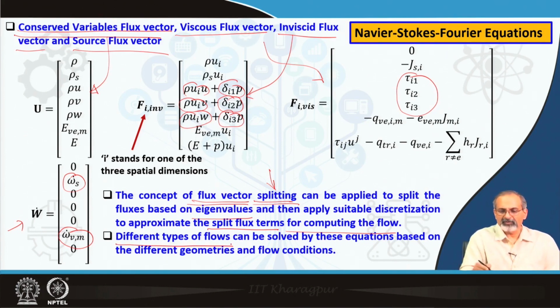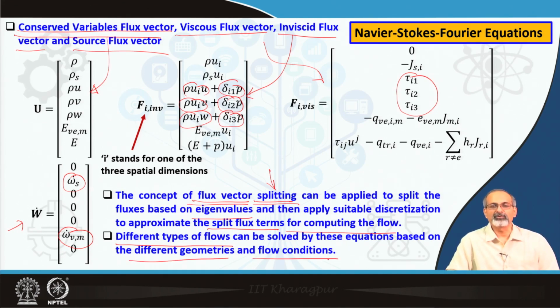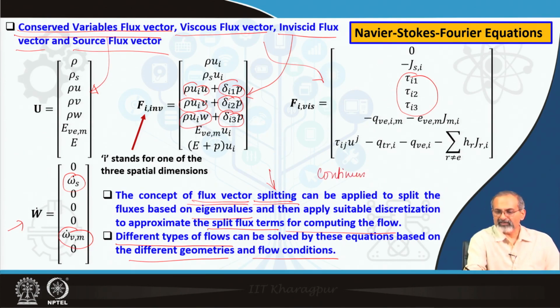Of course, different types of flows can be solved by using these equations based on the different geometries that you choose and the flow conditions that you impose. You can consider viscous, inviscid flows, equilibrium, non-equilibrium flows, reacting, non-reacting flows. All kinds of possibilities are manageable within this framework. You certainly need to look at one important assumption that you should be able to fulfill, that of continuum. This is an important assumption which should be fulfilled for these equations to work.